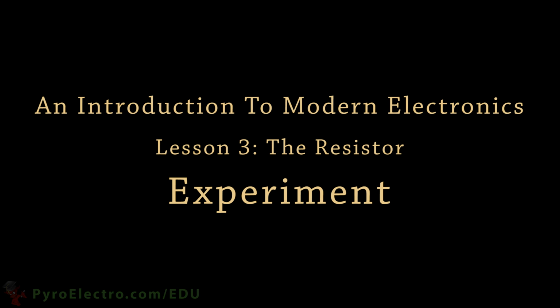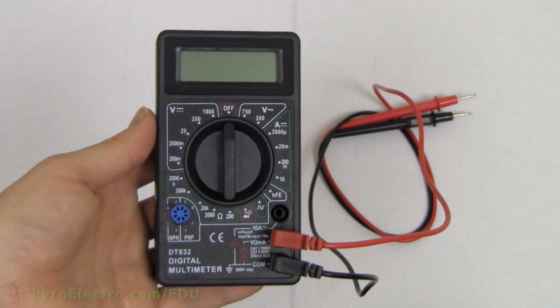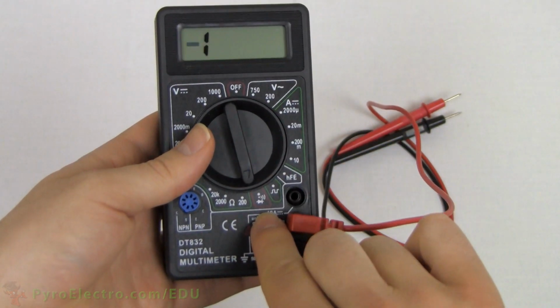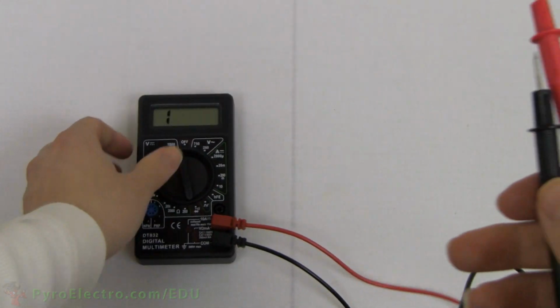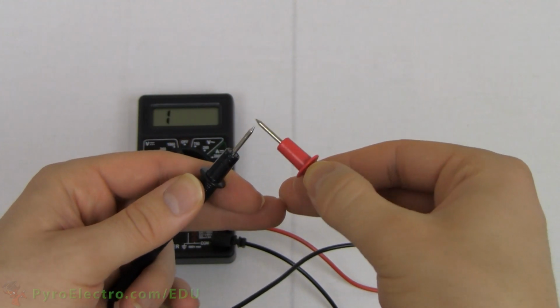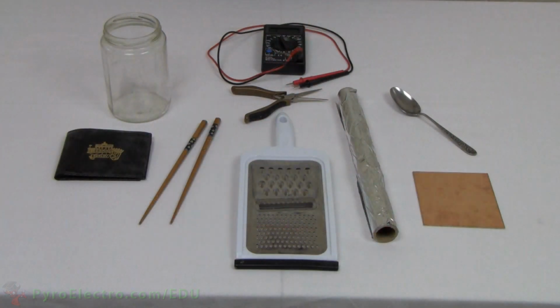Let's perform an experiment to see the difference between a conductor and an insulator. For this experiment, we will use a digital multimeter. Switch it to the continuity setting indicated by this wave-like symbol. If we touch the red and black probes together, you can hear a short beep. This beep indicates that electricity can easily flow out of the red probe and into the black one. This digital multimeter function is known as continuity testing.